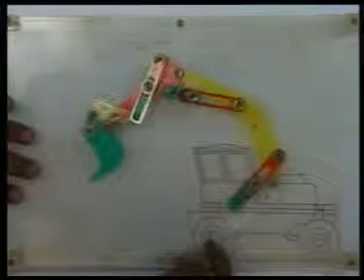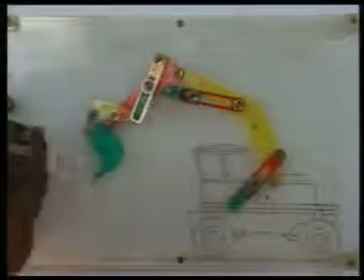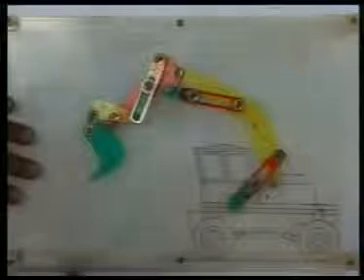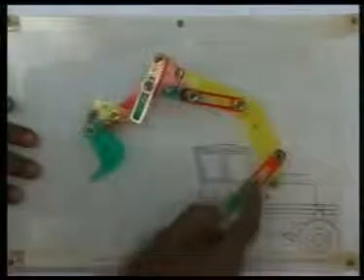an earth moving machinery. Here again, link number 1, the fixed link, is the body of this truck, and there are 11 other moving links: 2, 3, 4, 5, 6, 7, 8, 9, 10, 11 and 12. This 12th link is the output link, the bin of this earth moving machinery. There are 3 hydraulic actuators, that means there are 3 prismatic pairs here; the rest of the pairs are all revolute pairs. As these 3 hydraulic cylinders are moved,